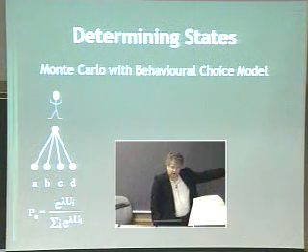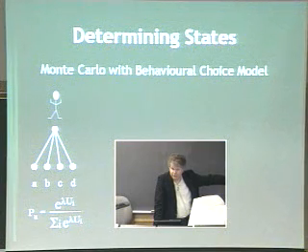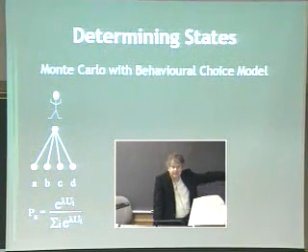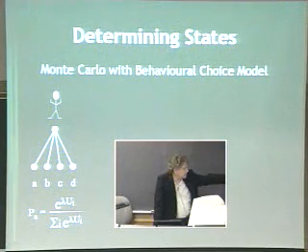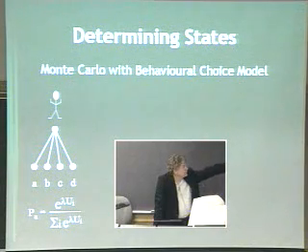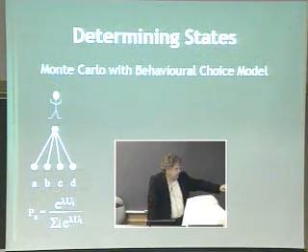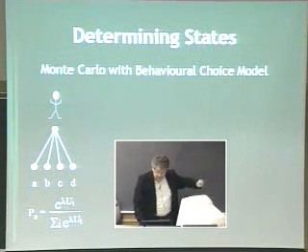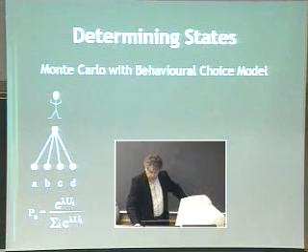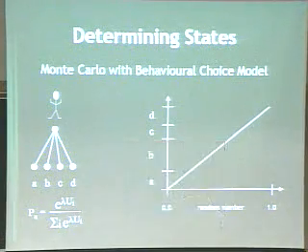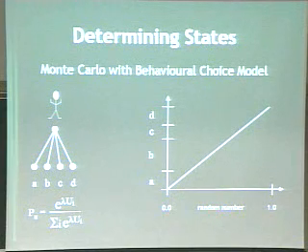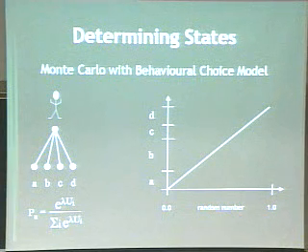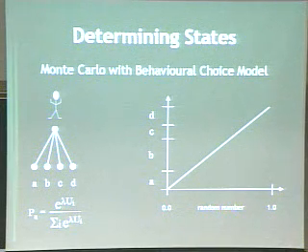And I can have what I hope is familiar to some of you, a formula of the logit model, that will have a utility associated with each of those alternatives, and I can put whatever I would like in the development of the model for things that influence the driver's decision among those 4 possibilities in my little logit model, and it will then assign probabilities for those 4 alternatives, and I can represent that on the y-axis of the diagram there, the 4 probabilities add up to 1, and then I can do a random number generation, just a standard uniform distribution for the random number generation on the x-axis there.